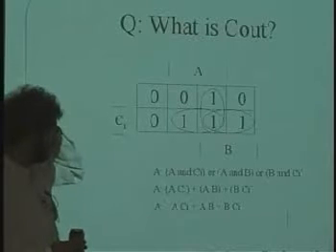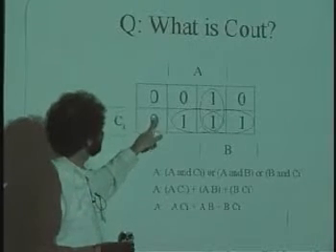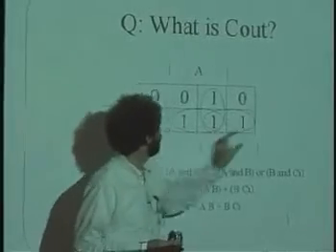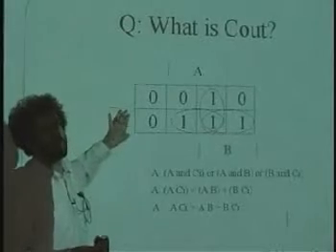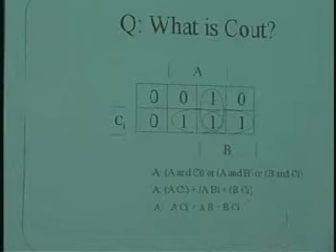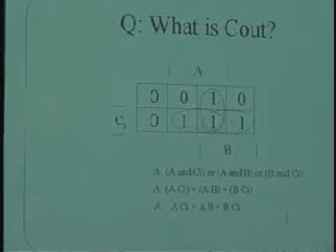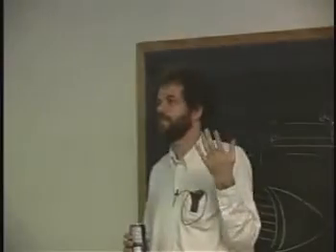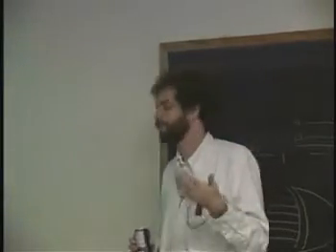Second rule you need to know is that, let's say that there was a 1 here and a 0 here, then you could have coalesced this one over here off to the right with this one over here off to the left. And again, you'll have practice doing that as well. And you only circle the ones. Well, there's actually 2 ways to do this, and in the recitation, I think you'll get practice doing it both ways. If you circle the ones, it has to do with the sum of products form, which is the OR of a bunch of ANDs. Guess what it is if you circle the zeros? Product of sums form. So you can do it the other way. Either way, you're just doing one of them. You're looking for groups. You are choosing one or the other, yes. You are not doing both.